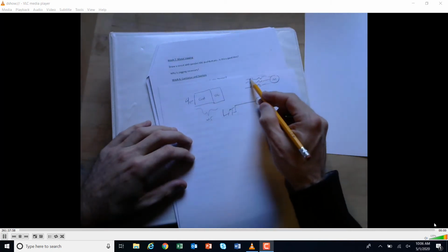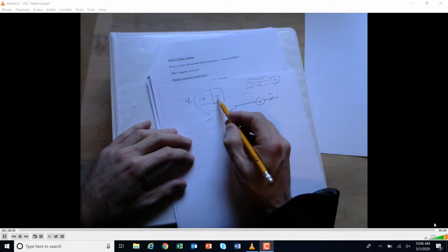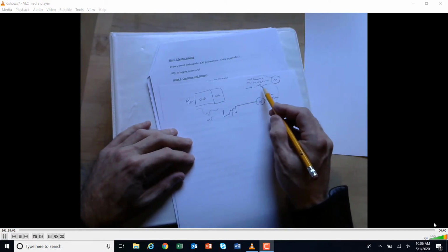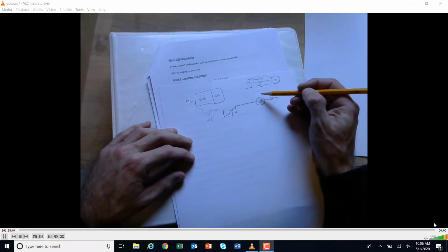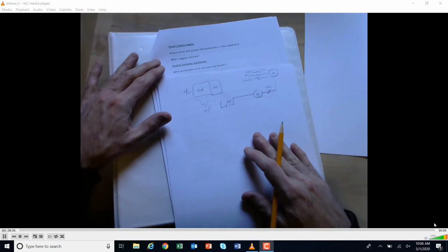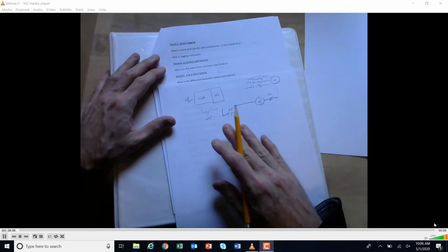These don't open. These are just heaters. That opens, which opens that, which opens the motor starter contacts. That's that device there. These devices are together. But when you put them all together, it's called a motor starter, but they still act independently of each other, okay? They're different items all combined into one.